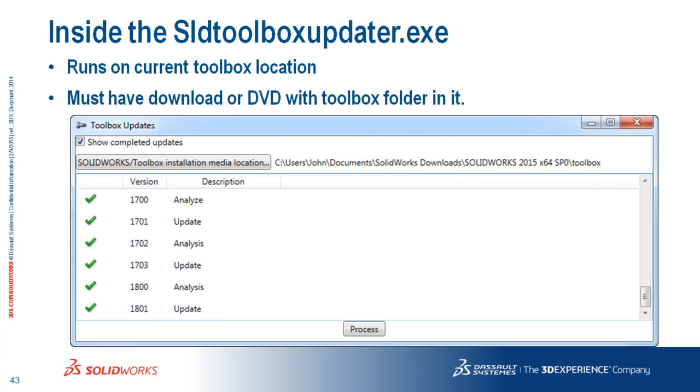To run this particular program, you will need to know where the SOLIDWORKS database that you're trying to fix is actually located. What happens is this program will use your Hole Wizard / Toolbox file location out of your option settings. It uses that location. It doesn't ask you for it here, okay? It assumes that location from the registry.